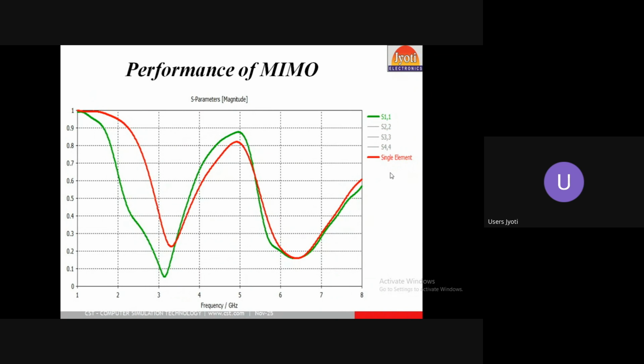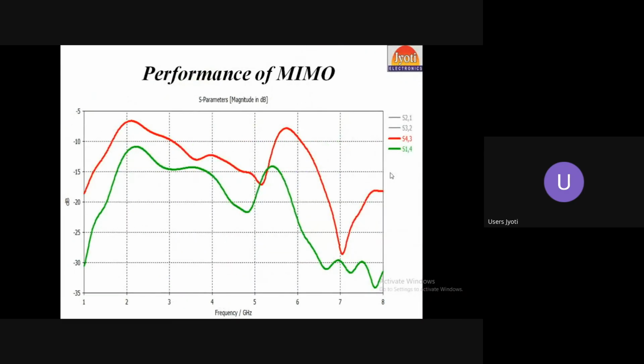So it will give the S11. S12 is also there. S12 denotes the first antenna to the second antenna, so the first antenna does not interfere with the second antenna's radiation pattern. It must be below minus 20 dB, which is good isolation for the MIMO antenna. If you are designing something like that, aim for minus 20 dB.